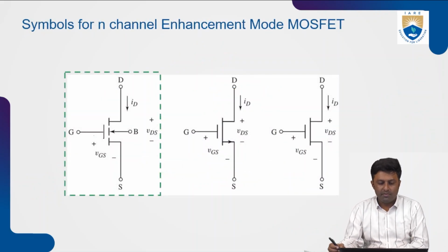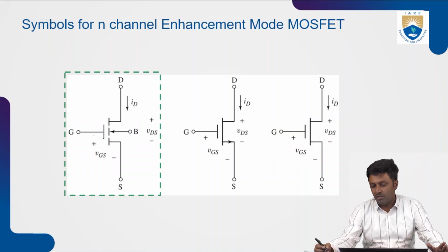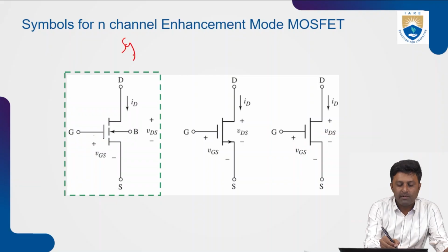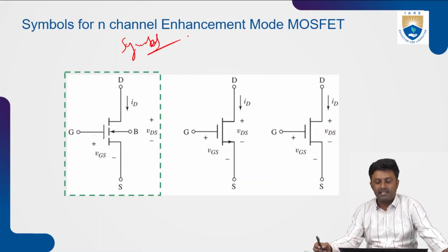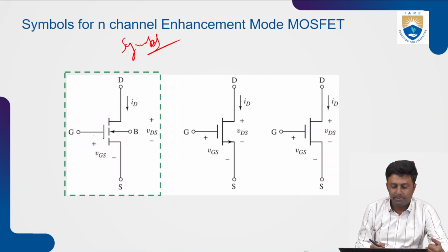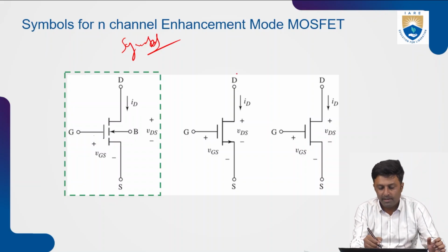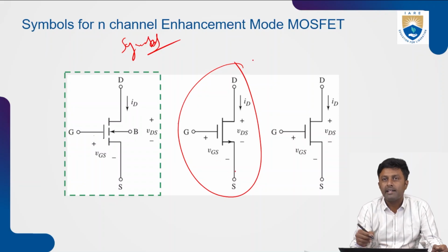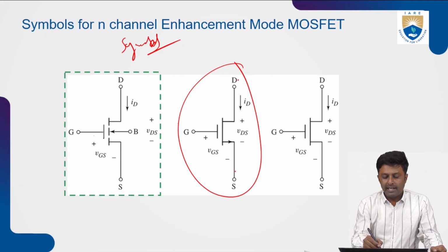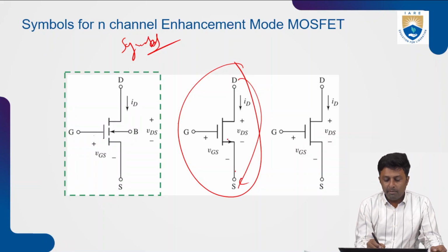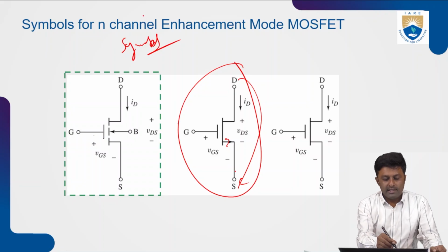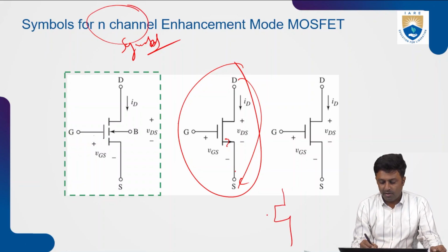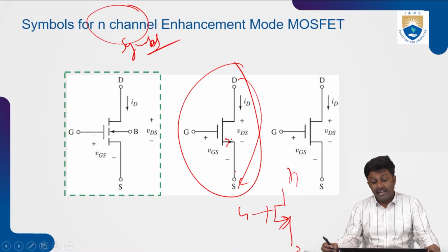So we have seen the different types of the transistors, that is mainly PMOS and NMOS. Now we will see the symbolic versions of these, because every time we cannot draw the diagram. Symbolically these transistors are represented. Like you will see about N-channel enhancement type. We'll remember this one, it is most widely used. So we have source, gate and the drain terminal here. This source and drain are interchangeable. If the arrow mark is towards outside, towards the source here, this is called N-channel. So if the arrow mark is outside, this is a symbol for the N-channel enhancement type transistor.